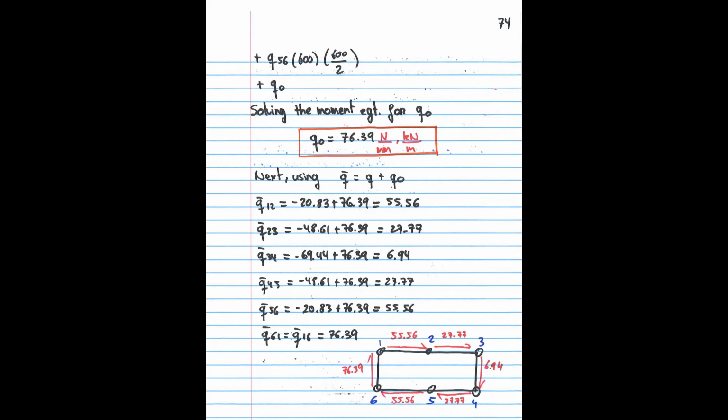The tedious part over here is that you need to find out how much of the shear force is supported by the stringers and how much is being supported by the panel. And because it's a change in taper, you need to find out how much is being carried by each one of the stringers, which is the tedious part. After that, it's basically the same thing we have been doing over and over.